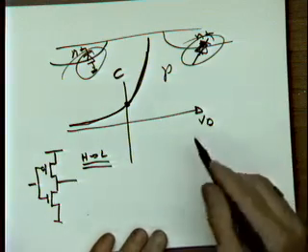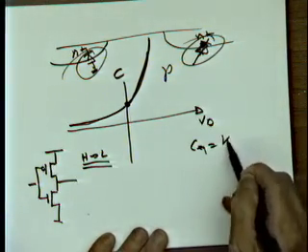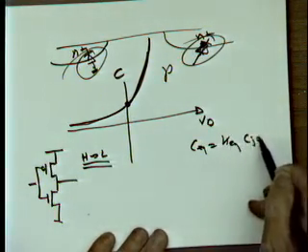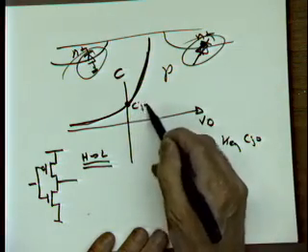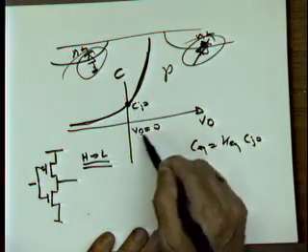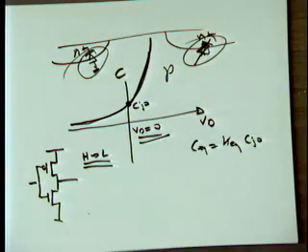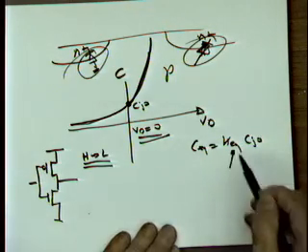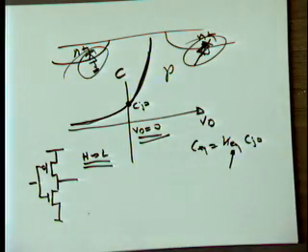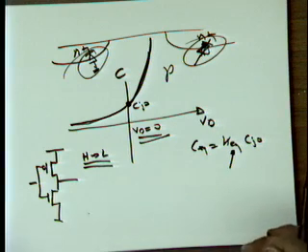It says C equivalent is equal to K equivalent times Cj0, and Cj0 is the capacitance for Vd equal to 0. Okay? So that's what we want to do. The question now is what values of the voltages should I plug into my K equivalent? And the answer is it really depends upon what transition you're considering.